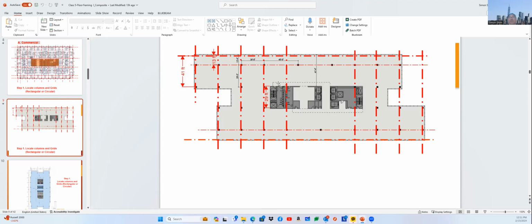The reason is you don't want to wait 1 minute to get to your office, right? So basically, this is for their vertical transportation study. How many seconds do you usually have to wait, right? How many minutes does it usually take to get to your office? This is important. So they need to really study, based upon human psychological factors, how patient people actually are waiting for their elevator. I think those are also key elements, so that they can decide on enough elevators. It's part of the vertical transportation system study.